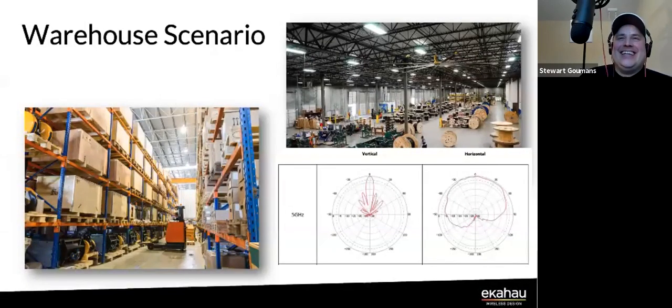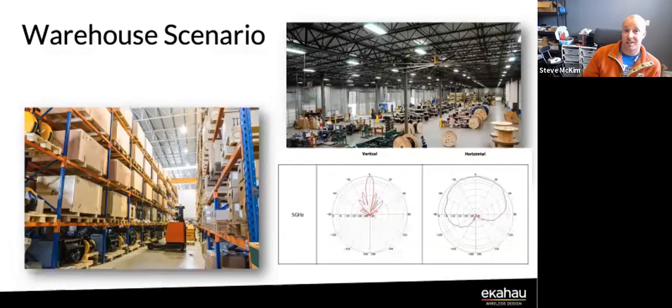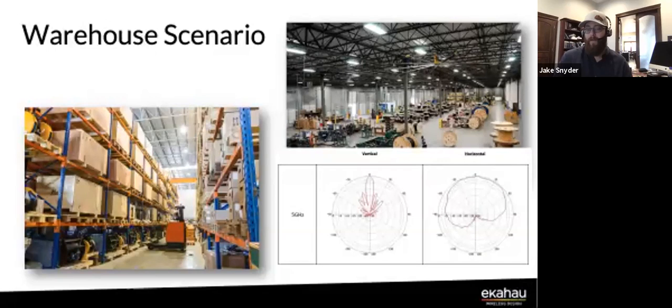No, it doesn't. Yeah, you need to pay attention to whether that's the 3 dB or 6 dB down point, right? Because that makes a big difference. Yep. So most antennas, not all, but most, rate beam width in terms of 3 dB from peak. A common one is a 6 dB patch antenna.